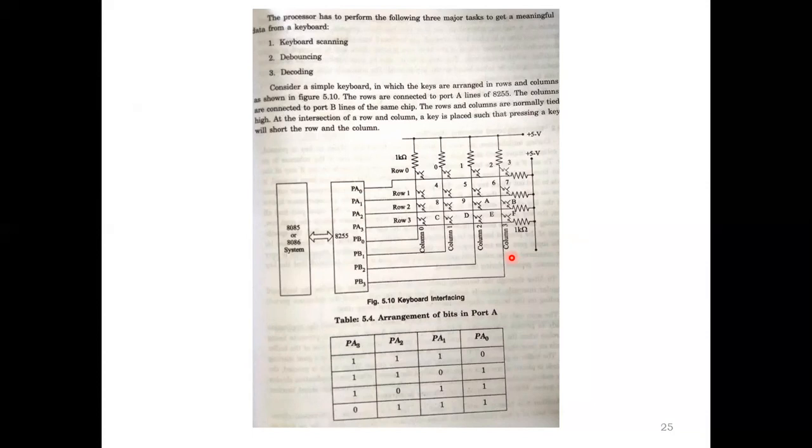If you are using 7 keys, you need to connect 7 keys with the particular port. If you connect them in series and you are using 20 or 30 keys, you have to increase the number of input output ports. That is not available in most systems, and it will increase the cost of the system. So the switches are connected in matrix format. For example, in this diagram, we connected 16 switches in matrix format, but we can access these 16 switches through 8 ports only. So the number of ports is reduced.